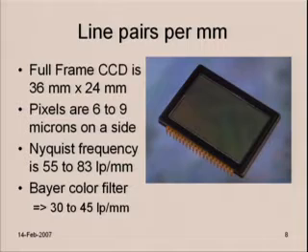So if you think about a set of 9 micron pixels covered with a panchromatic sensor that's not trying to capture color information, the highest frequency they can capture without aliasing would be alternating 9 micron stripes of dark and light on the sensor.